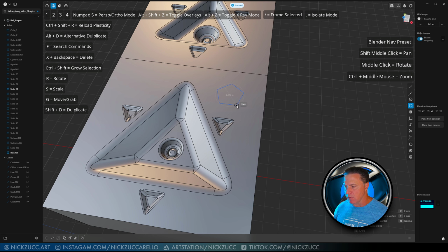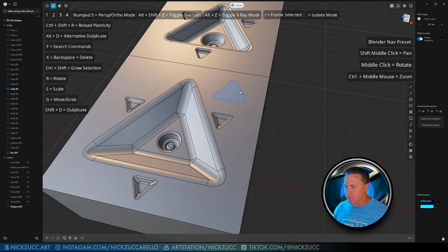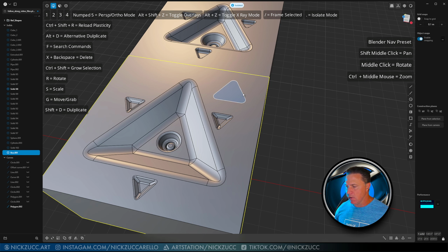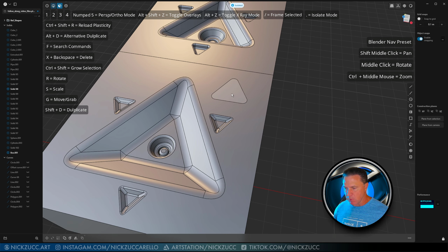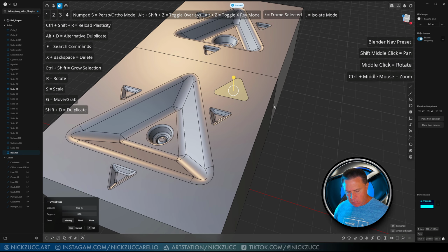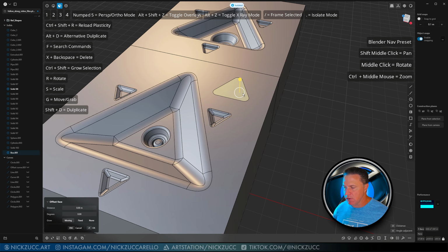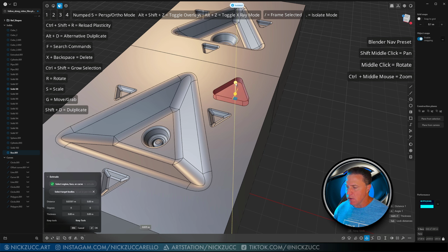I'm just going to click and drag out. We'll do Shift and roll the middle mouse like that. Okay. So we got the curve, right? And if we tap 1 on these points, we can select this, and we can tap B, and we can bevel the points on there. So if I do that, at that point, we'll just tap 2, and we can hit Shift I, imprint it on the body. Select this curve, just tap H, we'll hide it. And now at this point, if we tap 3, select this face again, hit E, and drag down.